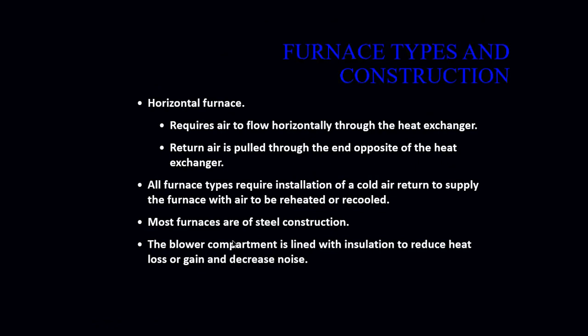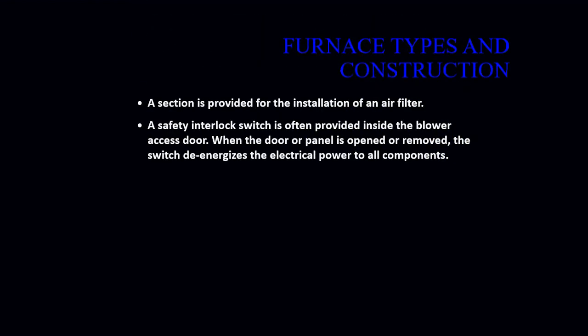Most of our furnaces are going to be constructed of some sort of steel, and your blower compartments are going to be lined with insulation to help reduce heat loss or heat gain, and also to reduce the noise that the blower will be making. The section is also provided for installation of your air filter.